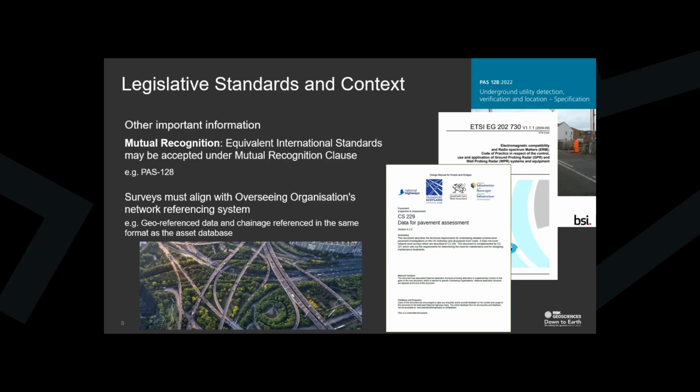And so all GPR operators must comply with Ofcom regulations on radio frequency broadcast and operate with an Ofcom GPR license. As part of that license, if we wish to work near sensitive sites such as airports or radio astronomy sites, both of which can suffer interference from our transmissions, we need to follow specific procedures to notify those sites.